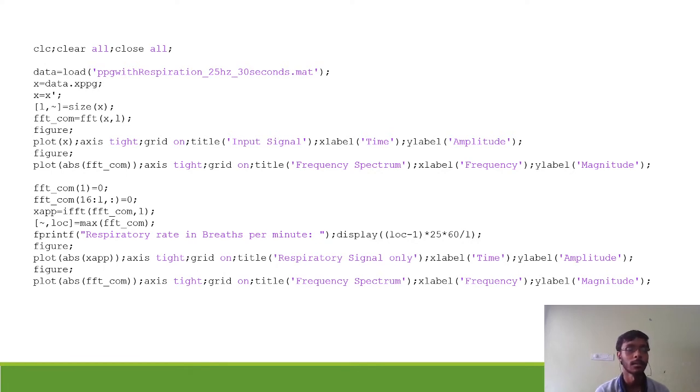If you calculate 0.05 with our sampling frequency and the total number of samples, there is a formula, k times Fs over N, so we can get the frequency from the index. We need 0.05 Hertz, so that will be around index 2, and 0.5 Hertz will be around index 16, so around 15. So we are taking from 16 up to the end of the samples, where the total size is L.